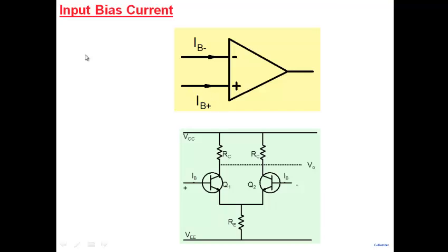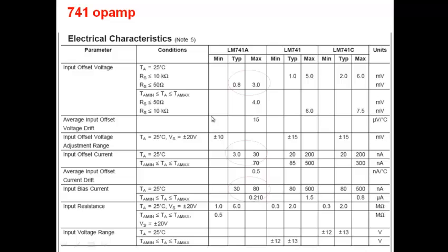So we also talk about input offset current. Input offset current is what? The difference of these two values. So you have the bias current, and then you can also talk about the difference between these two currents as well. That is called the input offset current. So that's another non-ideality to keep in mind, that I have these currents in my op-amp.